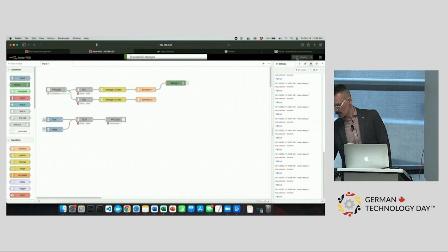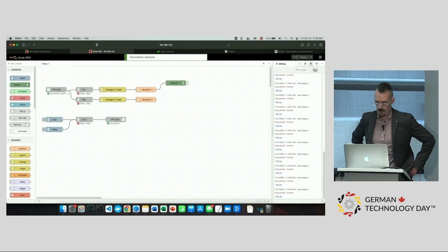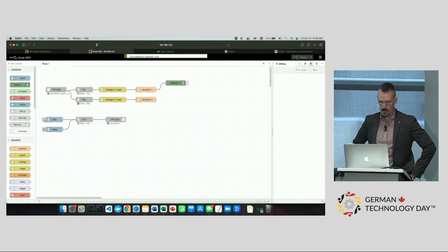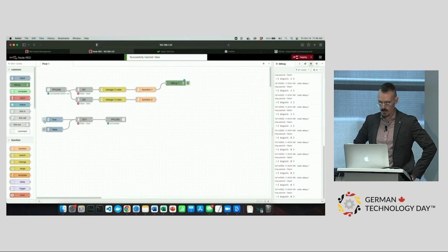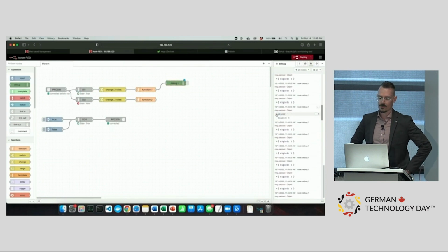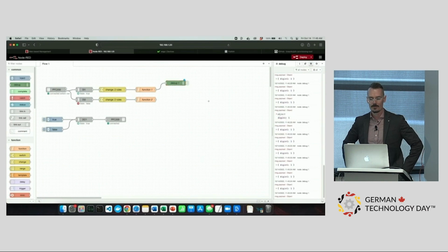And then I'm attaching my debug just to show you what the output of that looks like. So we're going to run it again. I'm going to clear it, press true. Turn on the debug. Cool. Now we have a nested structure. We actually have an object called digital input 1 that's sending out a 1 value.